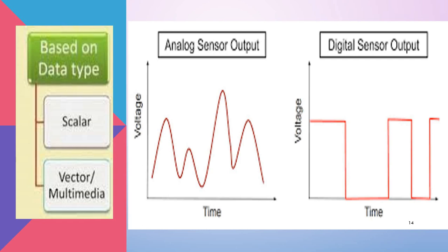So these vector sensors are things like inertial measurement units, compasses and 3D position tracking systems. All these are called vector sensors. And the final thing is the scalar. This measures and provides information about a single physical quantity, typically representing its magnitude or intensity. Here the scalar sensors utilize a single sensing element or component to measure the physical quantity of interest. And the sensing element may be temperature sensors, pressure sensors, light sensors, or some other dedicated sensors.